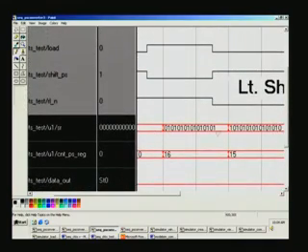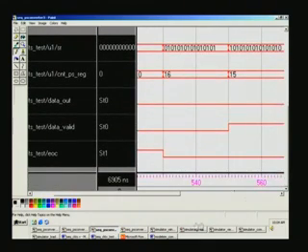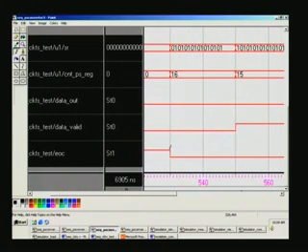So, you can see the same 0 1 0 pattern here, and once again this end of conversion is the previous end of conversion which we had processed. So, the moment you load a fresh data, that is reset. So, you have to take care of all intricate details while designing systems. And data valid was deasserted in the earlier cycle, so it will have to be asserted here the moment data starts flowing out.